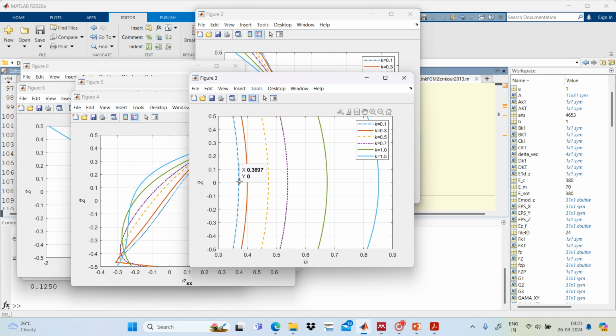while the ceramic part, that's having the least displacements, and it is 0.369. So if the material is completely made up of fully ceramic, then it would have the least displacements, while if it is made up of fully metals, it would have the largest displacements. But we know that both is having the drawback. If it is made up of fully ceramic, then we know that it's a tough material, means it is a brittle material, so therefore it would get cracked easily, while it's very good in thermal resistance, but it cannot resist the vibrations and all, it will get cracked.